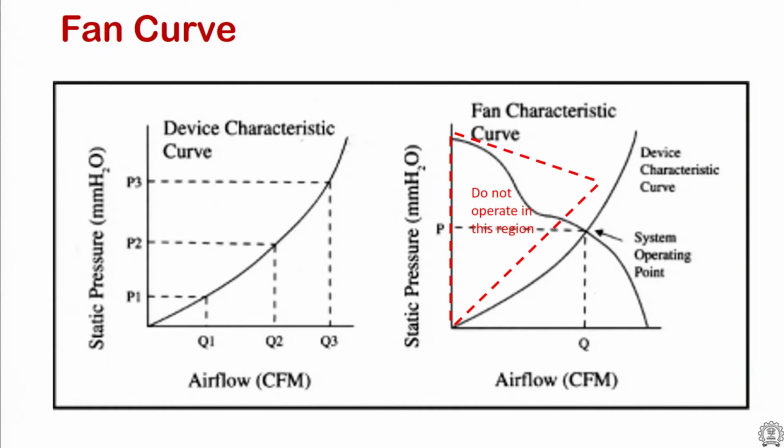That pressure drop is described in this line. For a given flow rate, there is a certain pressure drop across that heatsink, and that is often described by this curve, and where it intercepts the so-called fan curve is the operating point of a heatsink.